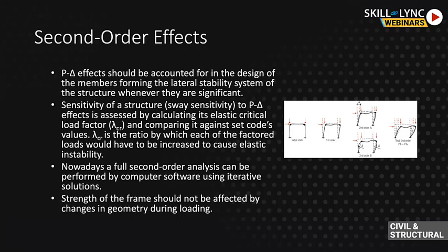The higher, the better. The good news is that nowadays computer analysis and design structural software are very powerful, and most of them enable you to carry out the full second order analysis. But again, you need to be mindful and you need to understand what the software is doing and not allow it just to make all the decisions on your behalf. The goal at the end of the day is to make sure that the strength of the frame should not be affected by changes in geometry during loading.